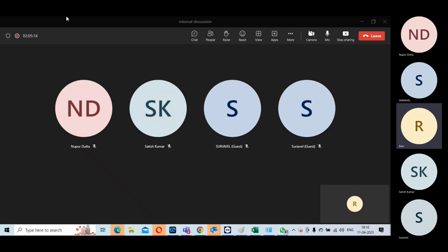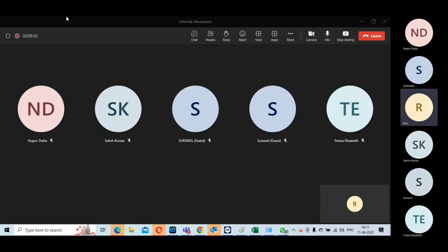Okay. CTS, actually there are a lot of things to talk about. I'll see what all I can talk about, because it will be an overfeed. It's a complex topic also. So one thing you have to look at: before you touch CTS, what you have to do is look at all the mux placement manually. Look at your clock tree structure. My mux is supposed to be placed over here.